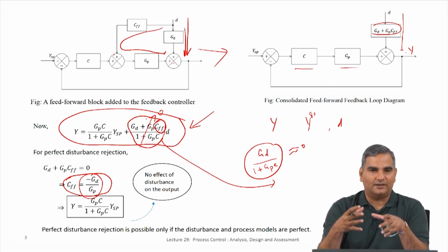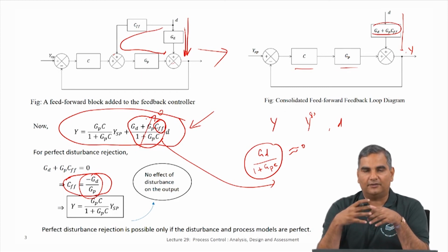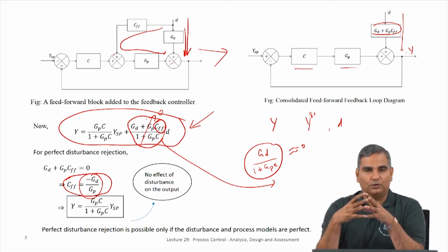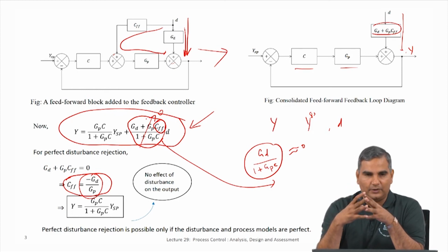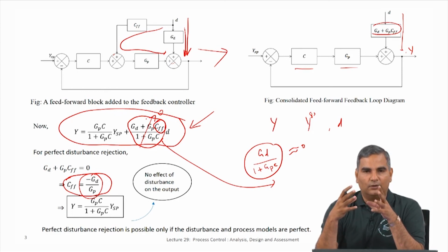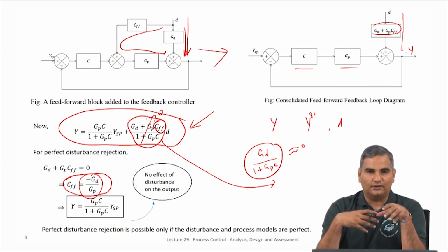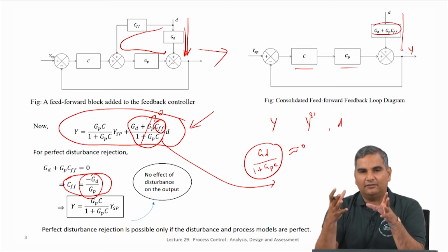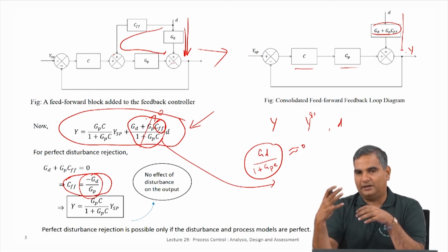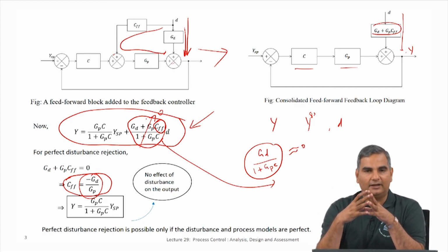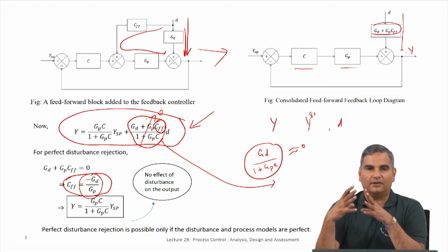In cascade control we have the stem position information, in feed forward control we have the disturbance information. Now that we have learned some of this, the next logical step is to look at a multivariable system, and I am going to do a 2 by 2, and that idea is very easily extendable to 3 by 3, 4 by 4 and so on. And then we ask the question, is there something that we can do to control this 2 by 2 system using SISO or single loop ideas? So, what other thing we might need to do that, and I am going to show you how this idea that we saw in feed forward can be translated to decoupling controllers, dynamic decoupling controllers. We will do one lecture on that to give you the next level of thinking in terms of multivariable control.